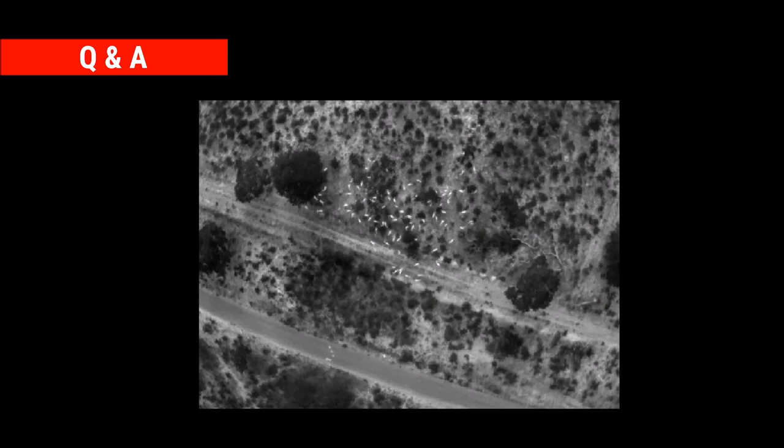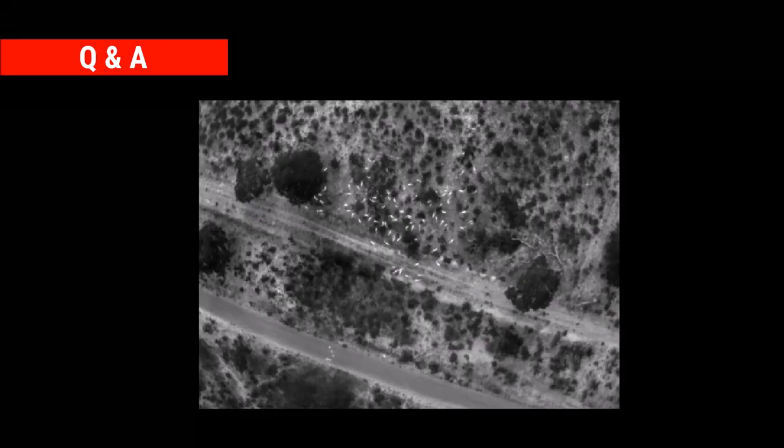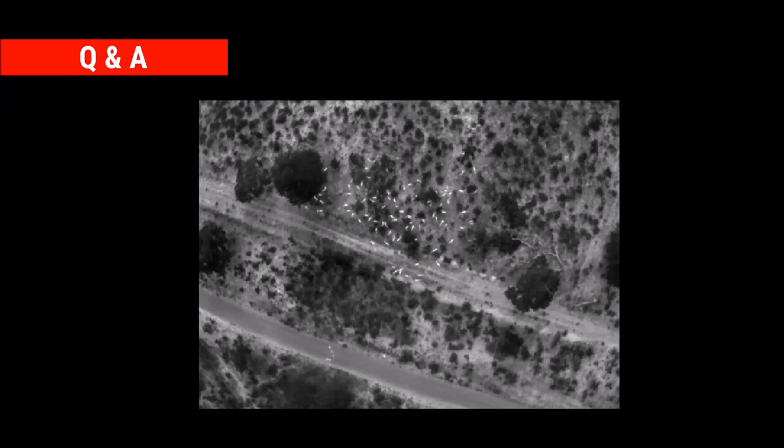So we generally fly at 100 meters to 125 to 150 meters, depending on what we're doing. If we want really high resolution, 50 to 60 meters has been our super sweet spot. What causes us to change elevation is actually the type of survey. We have more or less mentally broken down, is this just a wide area survey? Is this a specific site survey? Do we want to know information about a specific feature? And that more or less drives our decision-making, as well as comparability.